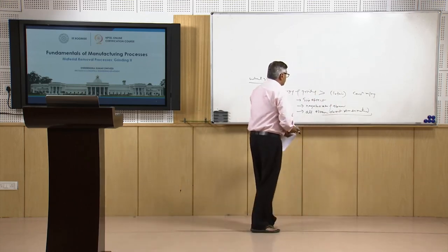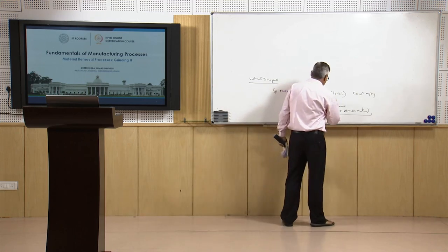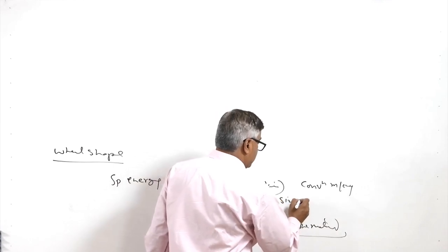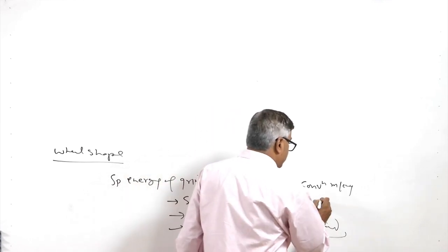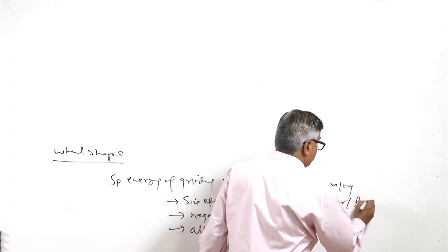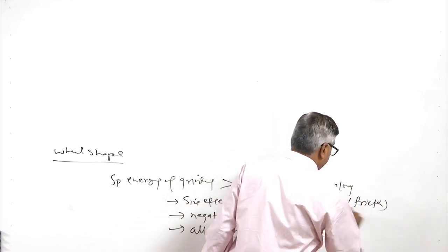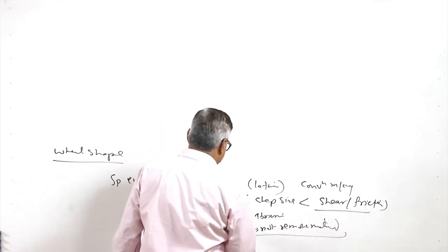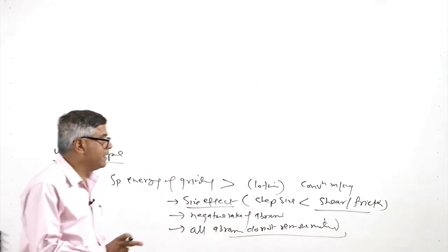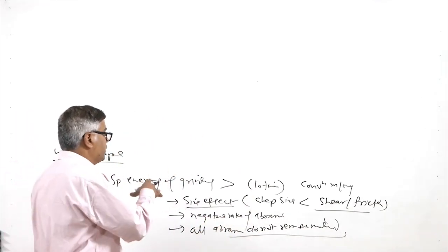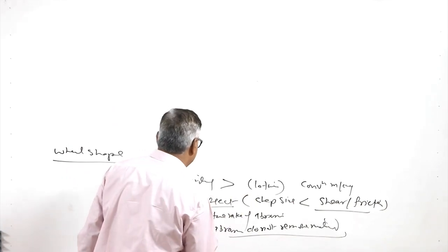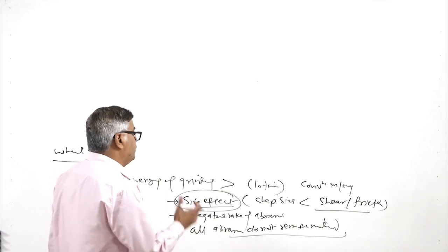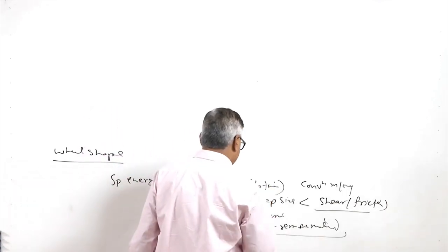So, when the chip size is less, it increases the shearing and the energy required for overcoming friction, in general, for a given volume of material. Since the chip size is very fine in grinding as compared to conventional machining, it leads to much higher energy consumption per unit volume as compared to conventional milling.